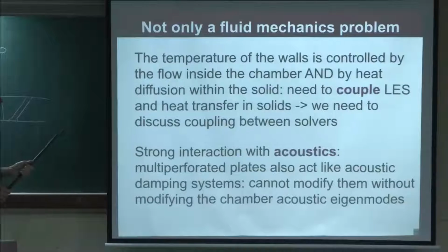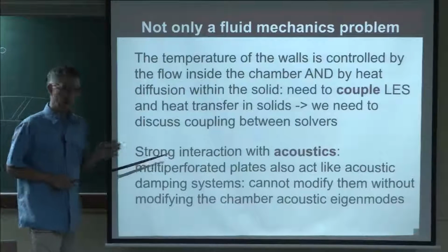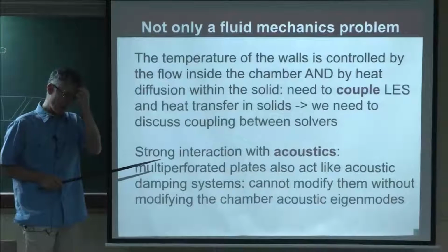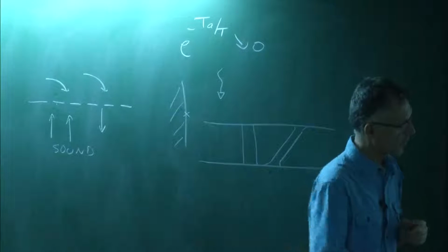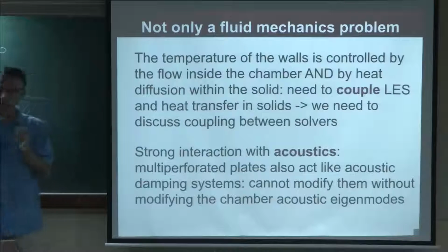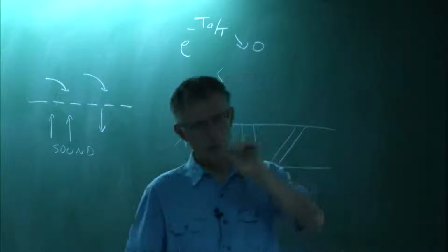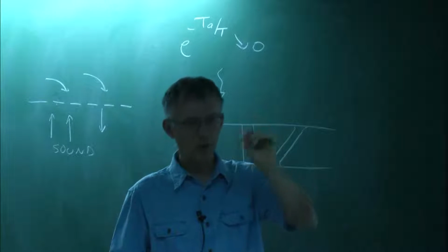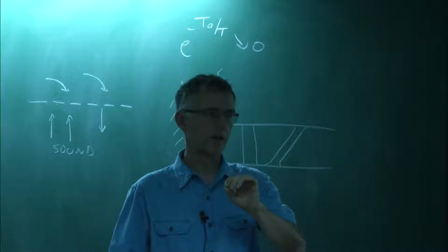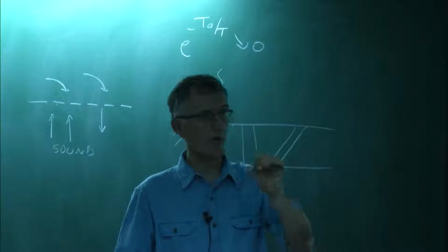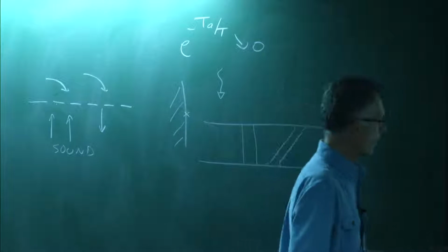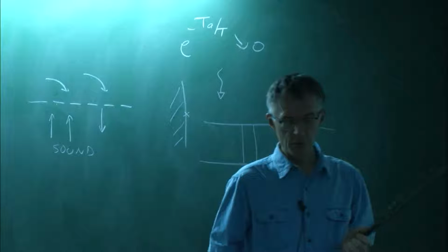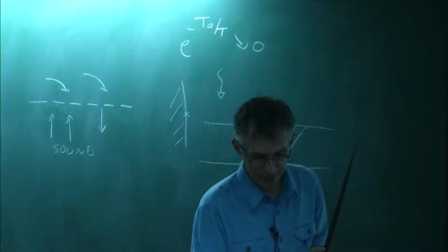And as I said too, it's not only about the flame itself or even the heat transfer itself, it's also about acoustics. Every time you modify the walls, putting in more holes, it will change the acoustics, so the engine might become stable or unstable, which will itself also change the flame. So, like always in these chambers, you have to be very careful when you start playing with these things.